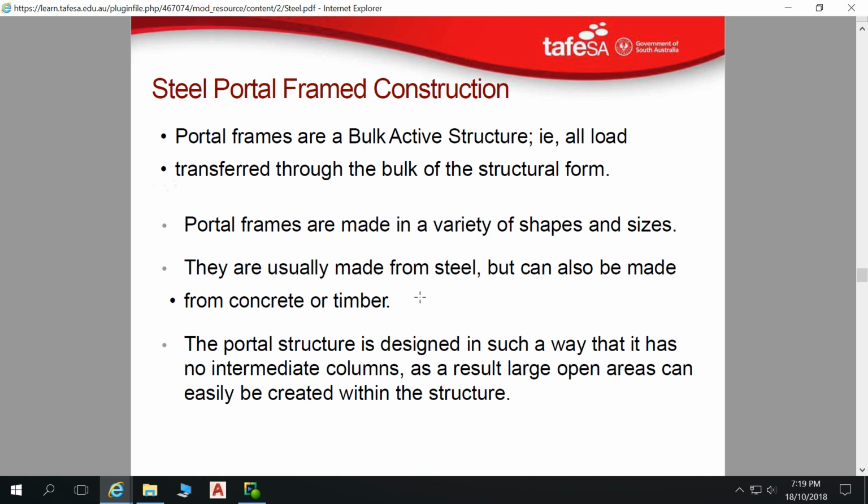So the steel sheeting provided shielding from the fire and a bit of separation between that shield and the timber portal frames. But those timber portal frames stood up to the heat really well. So where you get steel portal frames, they'll get hot and then they'll start buckling and they'll start falling and they get soft and they buckle. Whereas timber, its structure isn't affected by heat. So those timber portals could get really hot and that building maintained its structure. And because it maintained its structure, it maintained its integrity, so the fire couldn't make it into that building. And so it actually stood up really well to the fire.